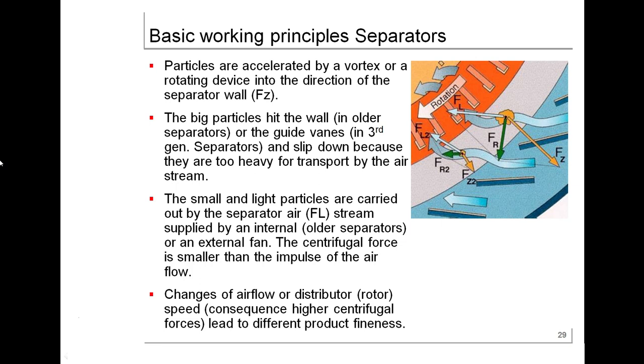The big particles hit the wall or the guide vanes and slip down because they are too heavy for transport by the airstream. The small and light particles are carried out by the separator airstream supplied by the internal or external fan. The centrifugal force is smaller than the impulse of the airflow. Changes of airflow or distribution speed lead to different product fineness.